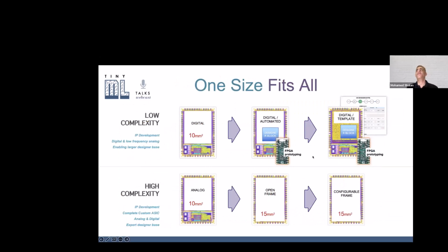However, not everyone wants to do this, because there are some advanced users who want to have the whole silicon area, which is 15 square millimeters, to do whatever they want. So we provide them with an empty Caravel, what we refer to as open frame, where we provide the pad frame, which contains the input-output pads.